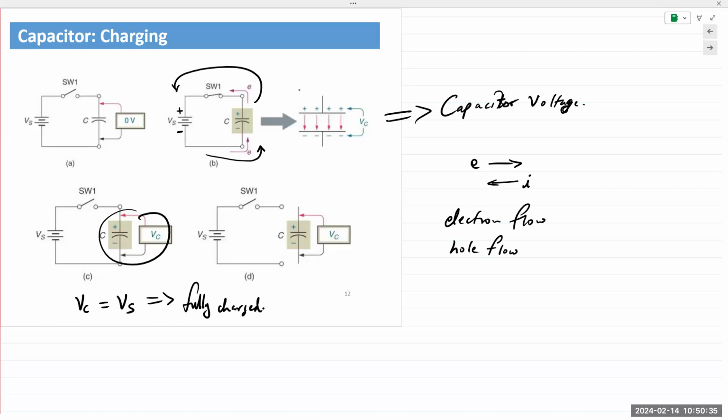Now, obviously, in real life, we would never connect a capacitor that cannot accept Vs. If a capacitor is rated for 8 volts and you apply 10 volts to it, you might damage the capacitor, depending on the physical construction of the material and how strong it is. So if you're applying 10 volts, you would always ensure that the capacitor can accept more than 10 volts.